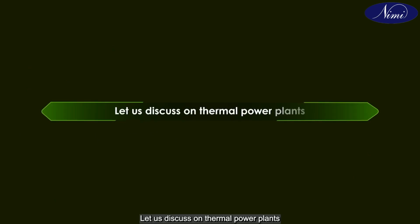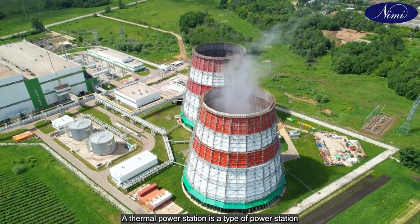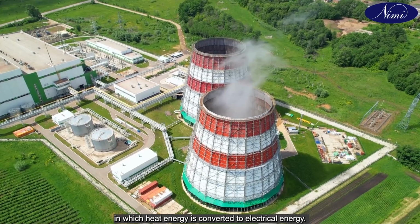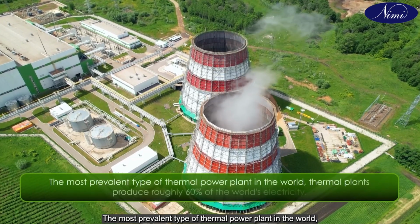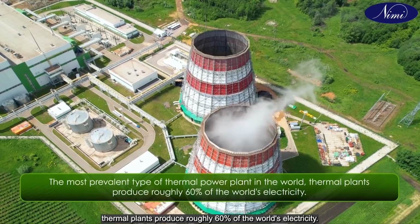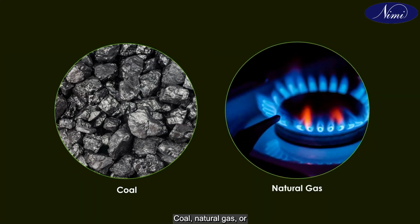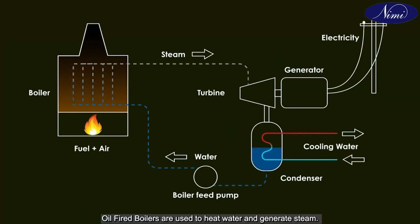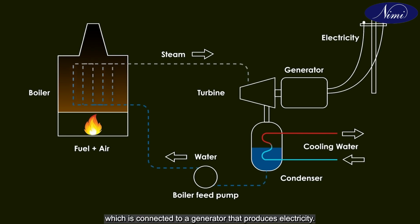Let us discuss thermal power plants. A thermal power station is a type of power station in which heat energy is converted to electrical energy. The most prevalent type of power plant in the world, thermal plants produce roughly 60% of the world's electricity. Coal, natural gas or oil-fired boilers are used to heat water and generate steam. The steam is then used to turn a turbine which is connected to a generator that produces electricity.